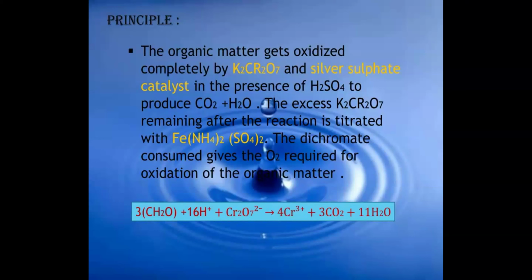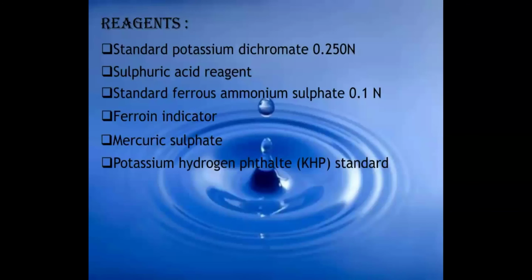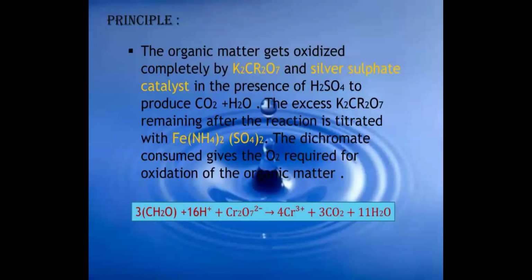The organic matter gets oxidized completely. Write the principle of measuring the COD in the laboratory. So the organic matter gets oxidized completely by K2Cr2O7 with silver sulfate. Note this point and these points and another.